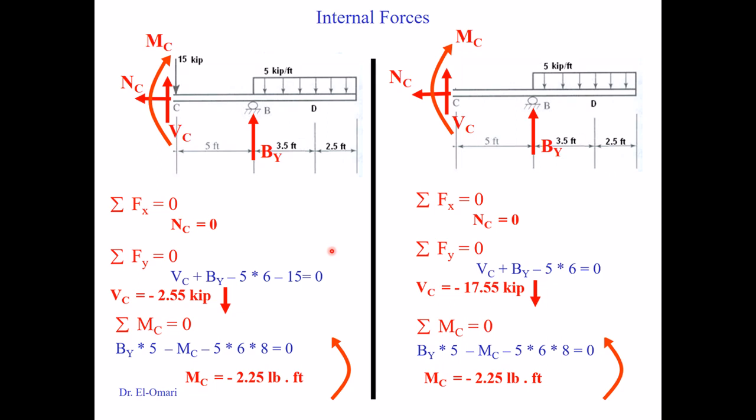A good observation and comment that you can see: when you cut here, we're always moving from the left, so you cut from the left and you see that 255, and then it will increase in negative because there's a drop. This is important when we work with shear moment diagrams. There's a drop. The difference increases from -2 to -17.55. This is the only difference, that concentrated load.